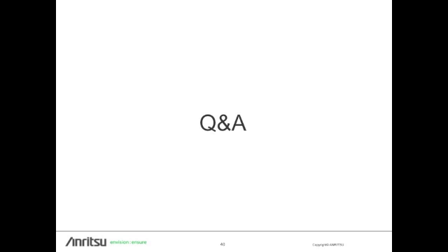All right, we've got time for just one more question. So, Eric, in your opinion, what is the best Anritsu tool for looking for low signal interference? MS2720T with the MA2700 and the highest gain antenna you can get, probably a Yagi.